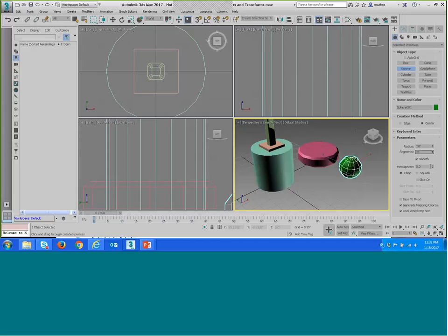And then I can use the hemisphere option right here to make it into half a sphere, because I want the lampshade under that housing. So for the hemisphere, I can use a 0.5, so it makes it into half a hemisphere right here.